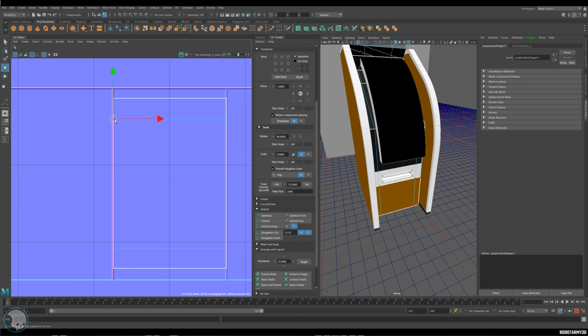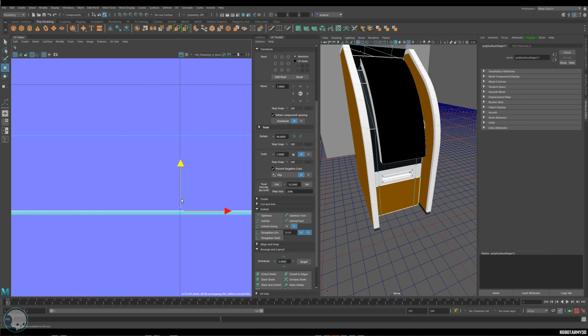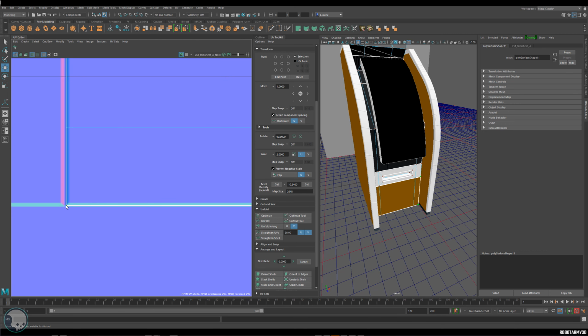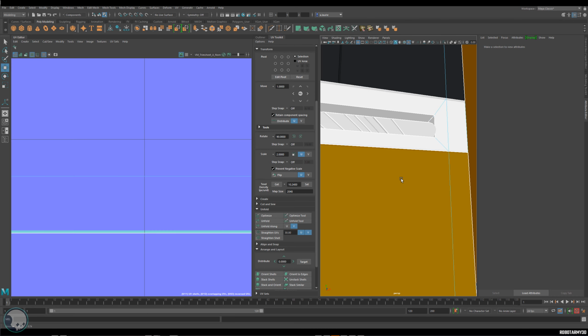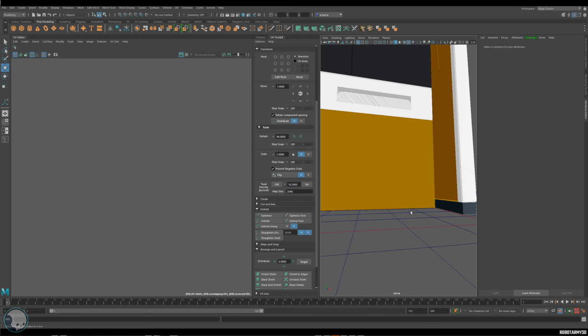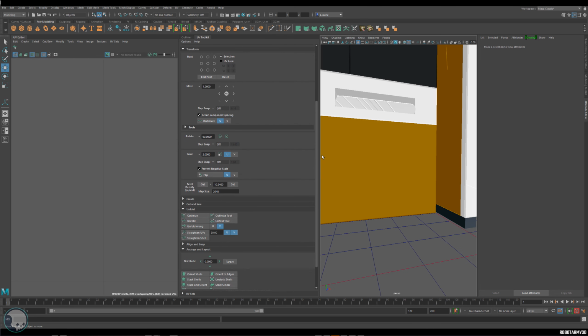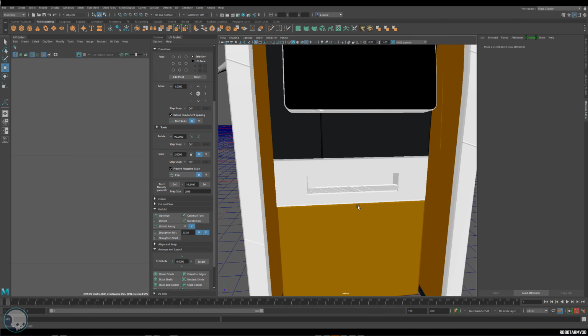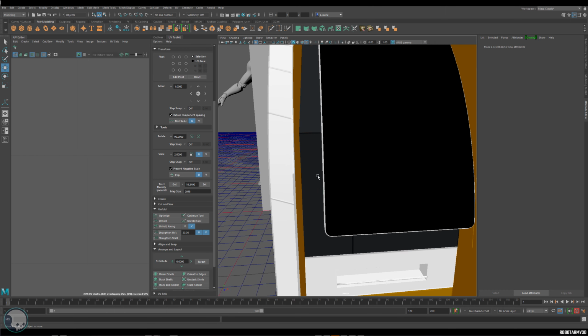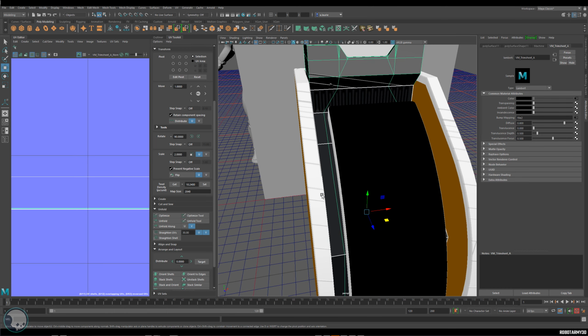And then I'm going to just select them all and then just scale it this way so it scales evenly across the whole face. Now that's the full panel line there because there's nothing next to it, so we can go all the way to the edge. Just check it over. Yep, that looks pretty neat. Let's have a little look what it looks like in window. Yeah, that's pretty good. So we've got panel loops now around the whole of that. That one wraps around, which is fine. Panel loop there. Let's see what else we've got.